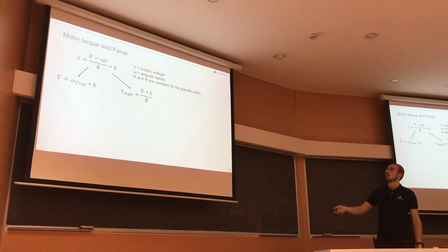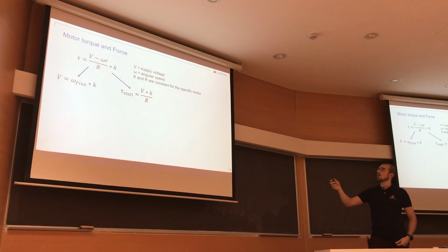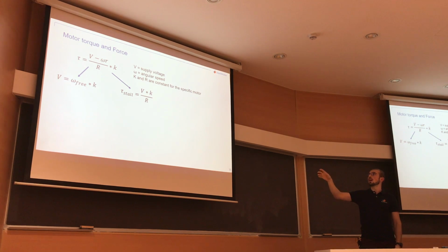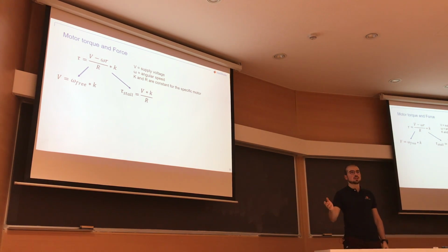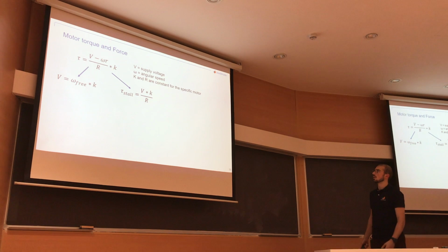We can now define the two extremes. The one with free motion, in the case we don't have any force on the motor. And then the opposite case, the stall, where I put so much torque on the motor that it cannot spin. So tau stall is the max force that it can apply. Meanwhile, the other is the velocity, the velocity that it can reach in the case it is free of any type of external forces.